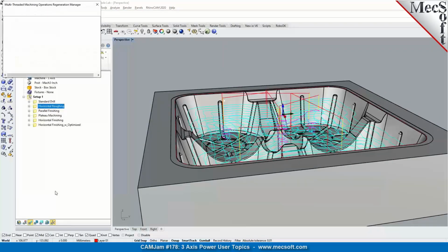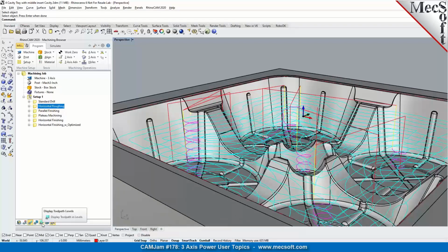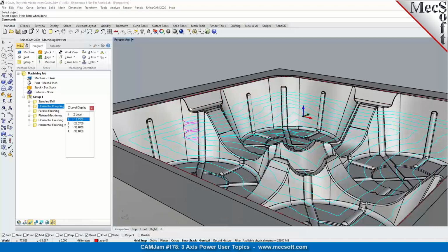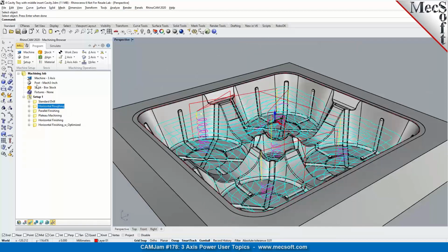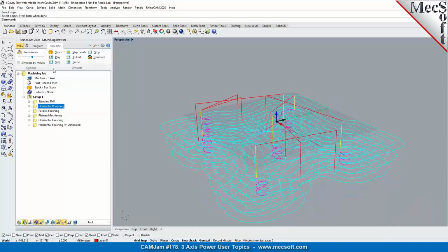Now generating the toolpath will plunge or create the ramp motion at the point you chose for your pre-drill location. So it's automatically going to move your entry to the location where this pre-drill point is. That gives you the control to specify where you want the cutter to enter on the roughing. Now this can also be done for both roughing and re-roughing operations, picking the start point.